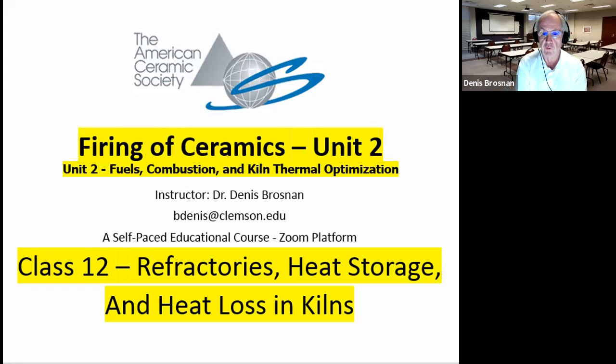We're in unit number 2, and in this unit, we've spent some time getting fuel into the furnace so that we can release energy into the furnace atmosphere so we can accomplish the sintering operation that we have chosen in processing our product. There was a lot of time dealt with getting fuel through regulators, through valves, into ratio regulators in order to get the right amount of fuel proportioned on ratio with the right amount of air.